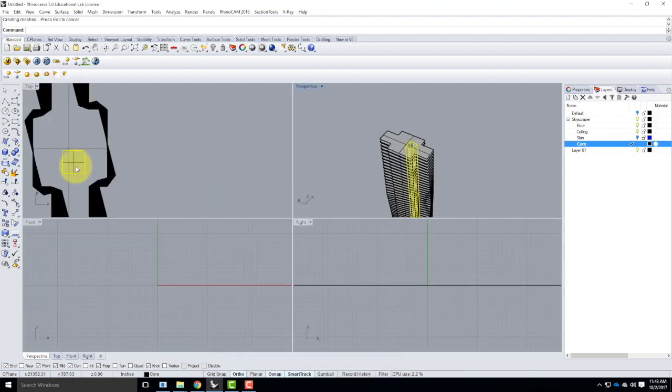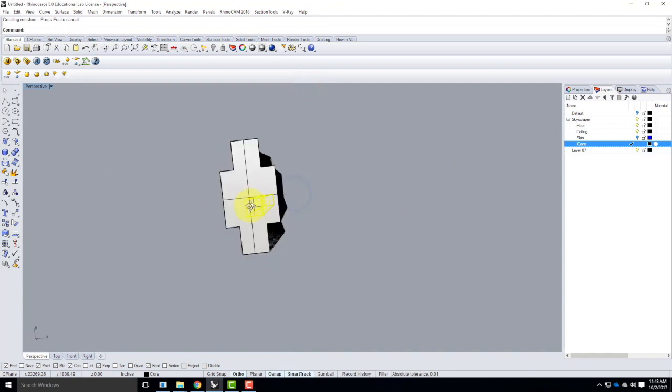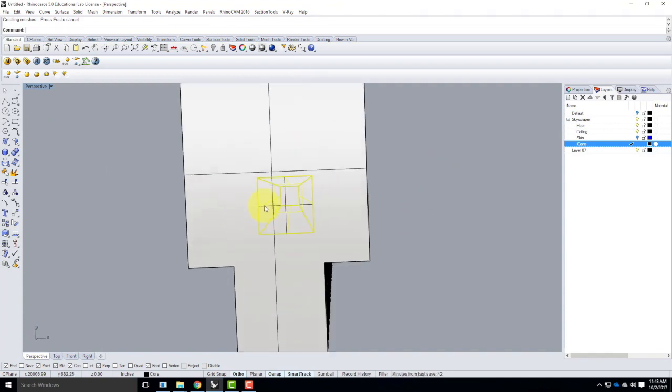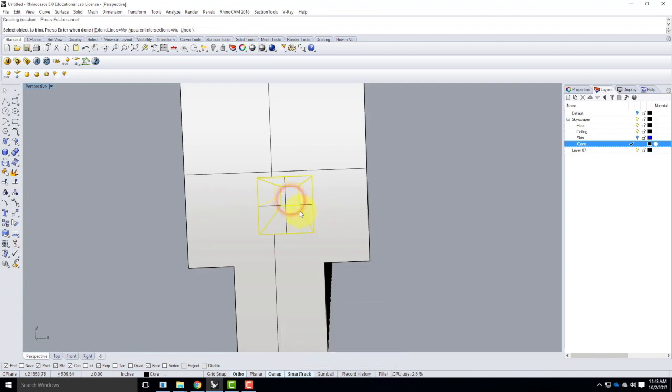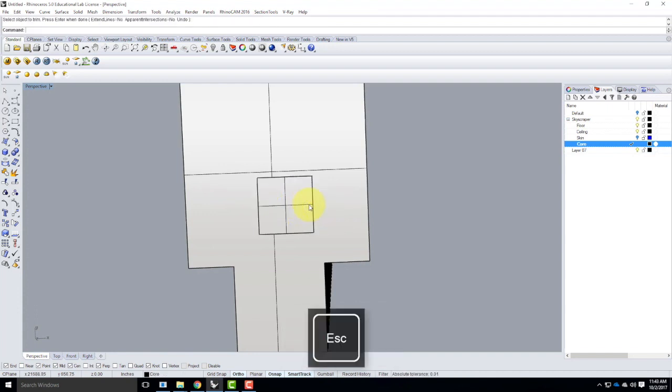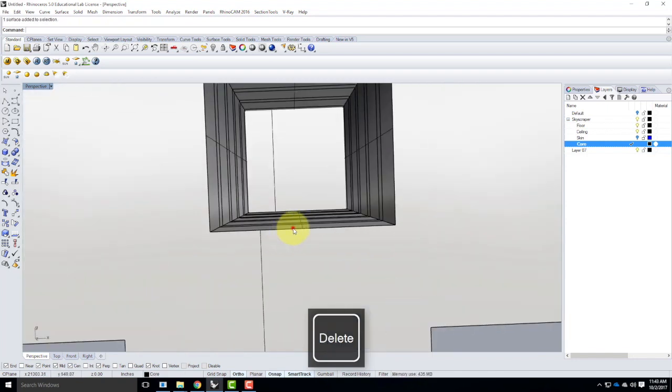And so I can do this in the top view, or I can set up my perspective view, which I always think is kind of entertaining, to look straight down through the core. And I'll type trim, and then I'm going to start clicking. And as I work my way down, oh, you know what? Let me get rid of this top so you guys can see it happen. Okay? Let me trim with this surface.